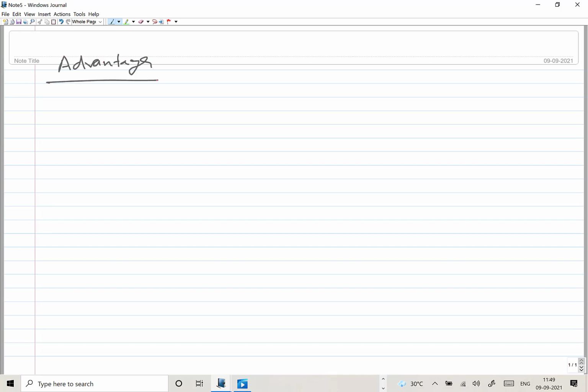of the friction welding. The problem here is that cleanliness is crucial in friction welding to avoid the presence of discontinuities, although some of these are removed. So you get the advantage of basically self-cleaning, because these impurities to some extent are pushed out, or these are burned due to the heat generation.